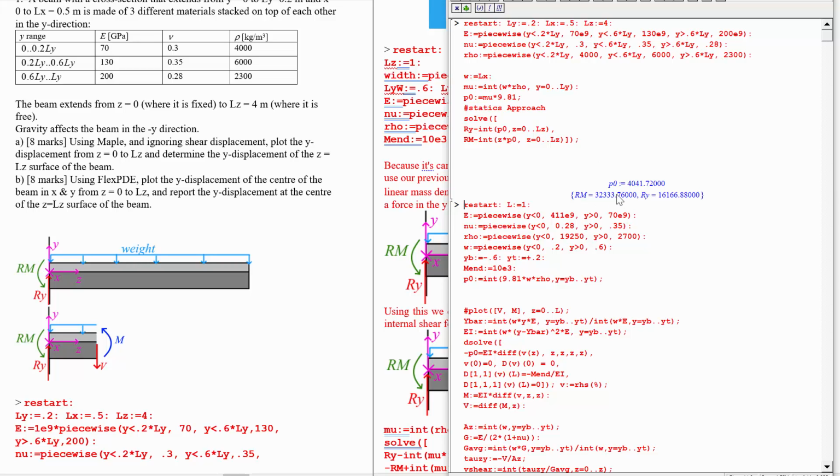The beam is kind of long in meters, right? If it was 2 meters, then you would expect that Rm and Ry would be numerically about the same, right? Because then the equivalent point of this distributed load is at 1 meter out, so you'd have the same reaction force as you would reaction moment. But for a 4 meter beam, you have a moment which ought to be around, or exactly, twice as big as the reaction force. So that is indeed what we get, and everything in the universe seems like it makes sense.